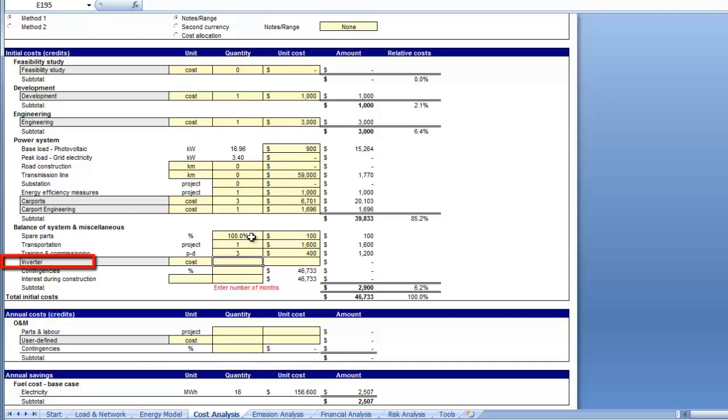Purchasing one 17 kilowatt inverter will likely be less expensive than purchasing 2 smaller units. Therefore, we will assume a SMA Sunny Tri-Power 3-phase grid-tied inverter rated at 17 kilowatts and with an extended warranty for $600 covering up to 25 years. The expected price is $5,815 with free shipping, so we will enter $6,415 as the inverter cost.